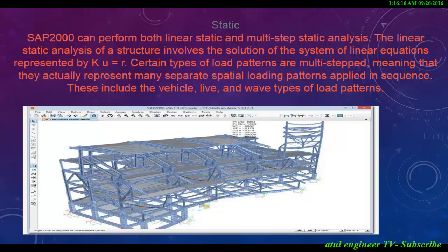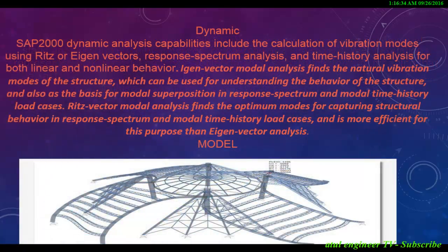Static. SAP2000 can perform both linear static and multi-step static analysis. The linear static analysis of a structure involves the solution of a system of linear equations represented by Ku = R. Certain types of load patterns are multi-stepped, meaning that they actually represent many separate spatial loading patterns applied in sequence. These include the vehicle, live, and wave types of load patterns.